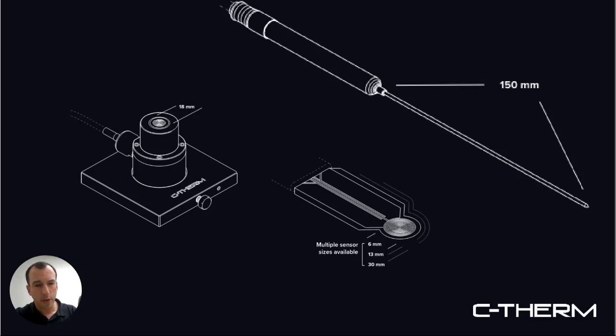So there's actually two circuits in that sensor. There's the main sensor coil, which is the active sensor, and then there's also a heated ring that goes around it. And that's to ensure that you get a one-dimensional heat flow into the sample material. This is very important from the perspective of measuring the effusivity and conductivity of the material accurately in employing a single-sided sensor.